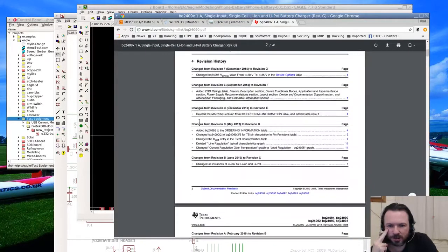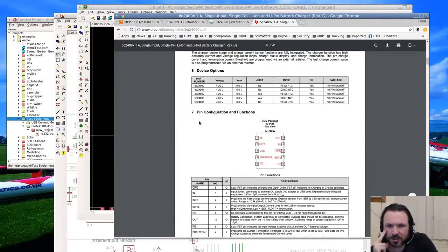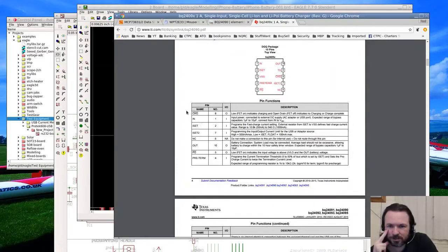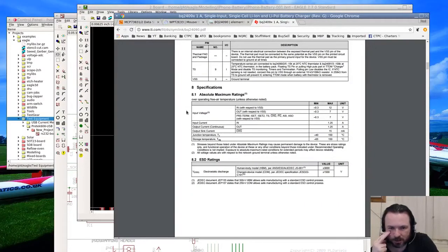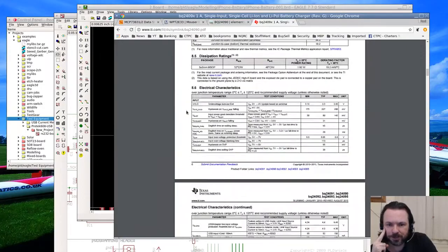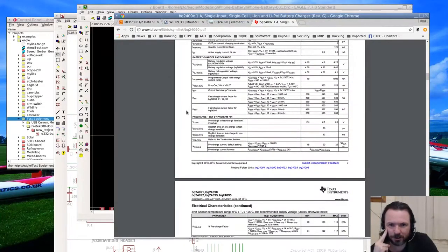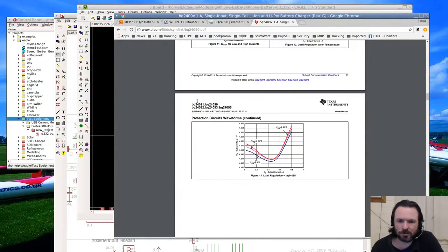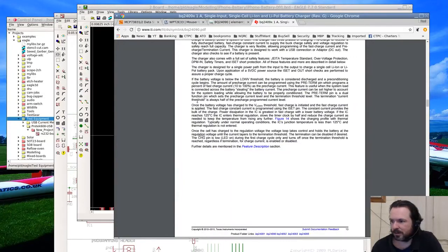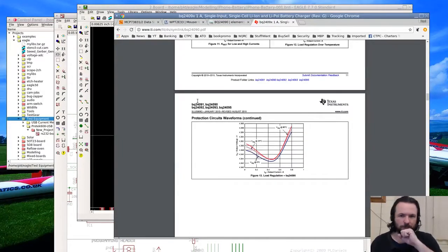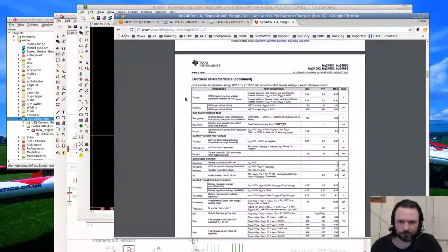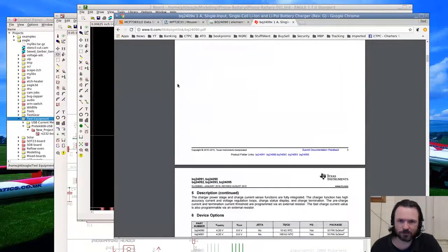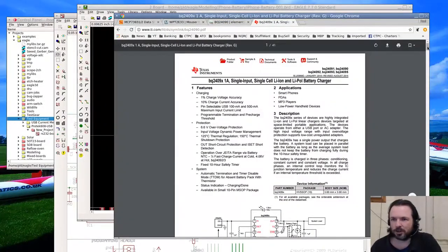The default current coming out of a USB port tends to be fairly limited, unless I tweak it with the right resistor values on the data lines to get it up to 1 amp or so. I may have to consider just externally powering this from a brick or something. It just would have been nice if it was all run through one USB connection. Oh, I can always explore the option.